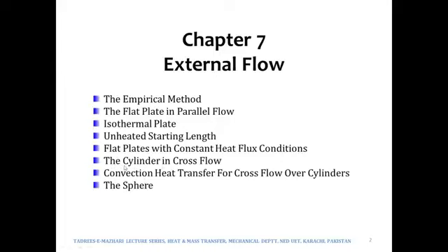And then we will discuss the flow over the cylinder and the sphere, and the corresponding convection heat transfer for the cross flow over cylinders and in case of sphere as well. Chapter 7 in fact mainly deals with a lot of Nusselt number expressions. So in this chapter we have a table at the end of this book which we would be using very frequently, and that list has got various expressions of Nusselt number.